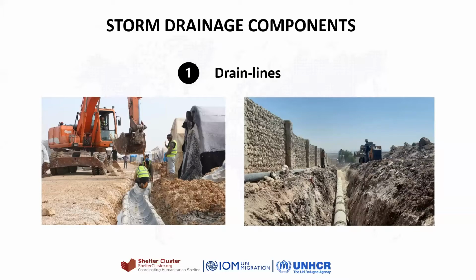Regarding the disadvantages of open drain lines, it makes movement difficult in some areas or for vehicles. But for the closed ones, if it is closed in a certain place, it is going to be a little bit difficult to do maintenance work, and the cost implications are going to be higher.